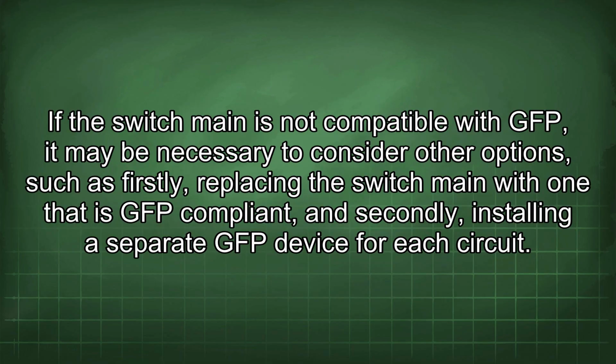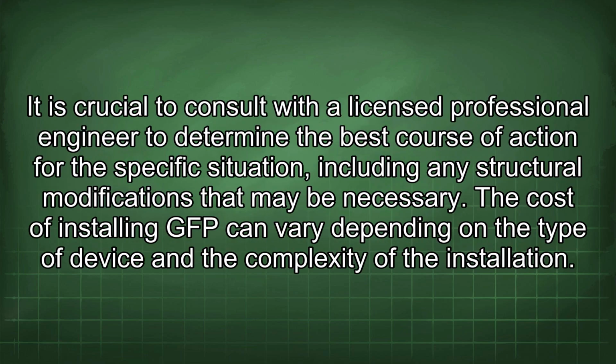If the switch main is not compatible with GFP, it may be necessary to consider other options, such as firstly, replacing the switch main with one that is GFP compliant, and secondly, installing a separate GFP device for each circuit. It is crucial to consult with a licensed professional engineer to determine the best course of action for the specific situation, including any structural modifications that may be necessary.